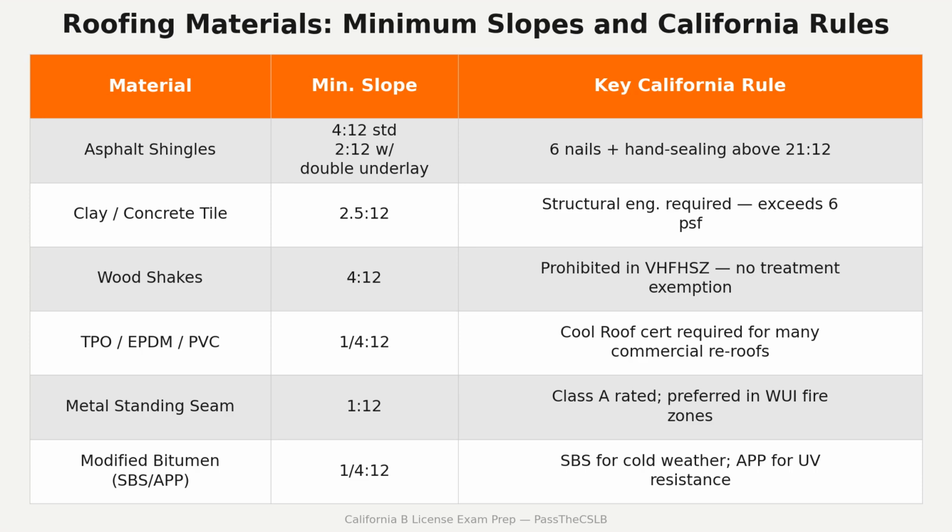Now picture a chin-up bar bolted to the ceiling. Rafters hang from it instead of leaning against it. The bar carries the load. That is the ridge beam, structural, supported at both ends by posts. Rafters in this system are in tension, not compression.